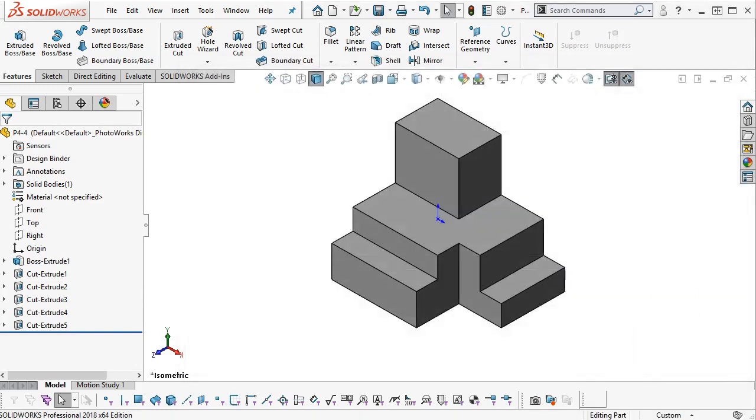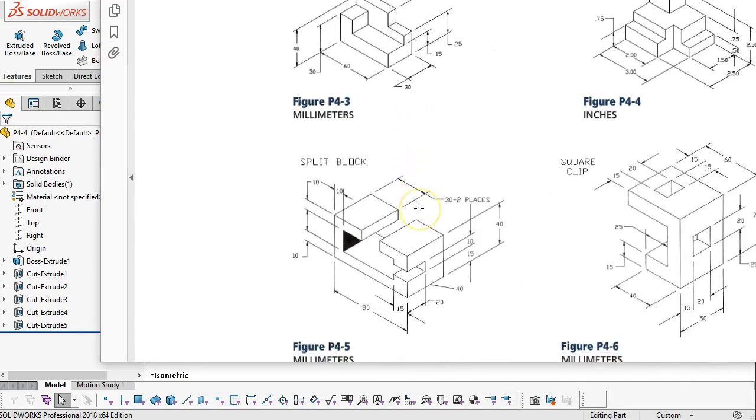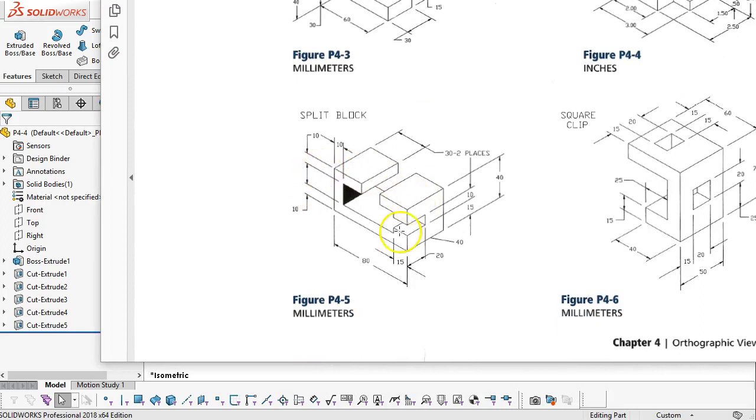4-4. All right, moving on to 4-5, block with material. We could do this as an offset or a thin feature. So let's see, this one's 15, 15, 16, 40. Don't really have a dimension there, so. All right, so in this one, 10 millimeters, 10 millimeters, aside from the step, which is 15 millimeters. So this one's not going to be a candidate for a thin feature because we have one dimension that is off.